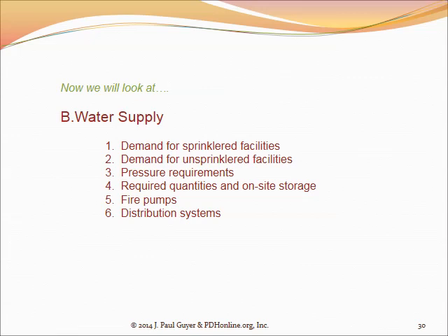Now let's move here to this Chapter 2 and look at water supply, which is something that, as I say, you don't tend to think about when you're designing a building. You just assume that there's going to be enough water out there in the street, in the city water line, to provide fire protection for your building. But that's not necessarily the case.